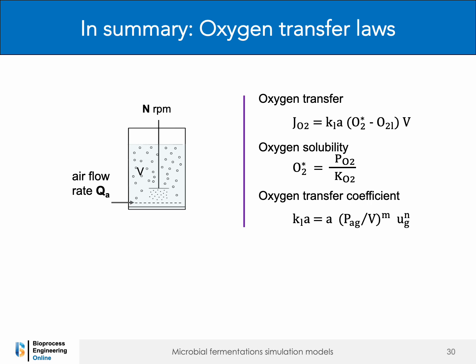In summary, the fermentation aeration process is modeled using the thermodynamic law of oxygen solubility and the kinetic law of oxygen transfer, in which the oxygen transfer coefficient KLA is correlated with the fermenter's agitation power and airflow rate.